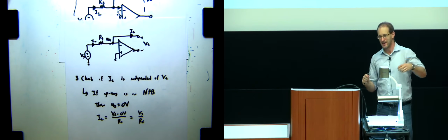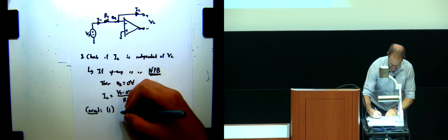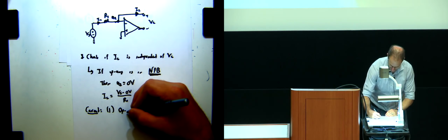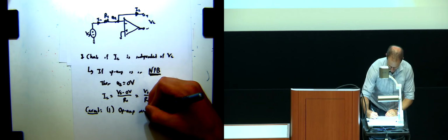In fact, as you just said, if this is like an open circuit, there's no feedback, so the thing doesn't actually work. So this is indeed the first and important caveat. When I say caveat, what I mean is that we mostly met our design goal, but there's two things we have to be careful of that, if they're not satisfied, the design actually will not work. And that first one, indeed, is exactly that the op-amp must be in negative feedback.